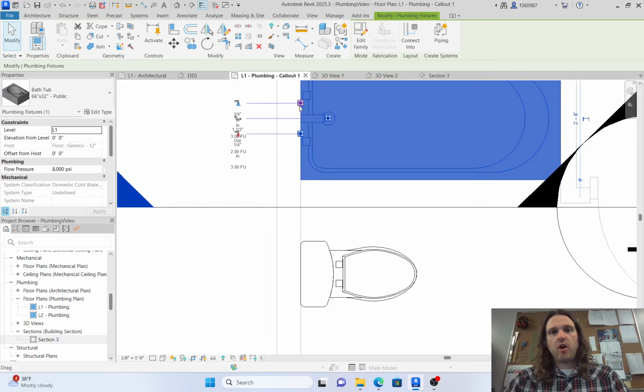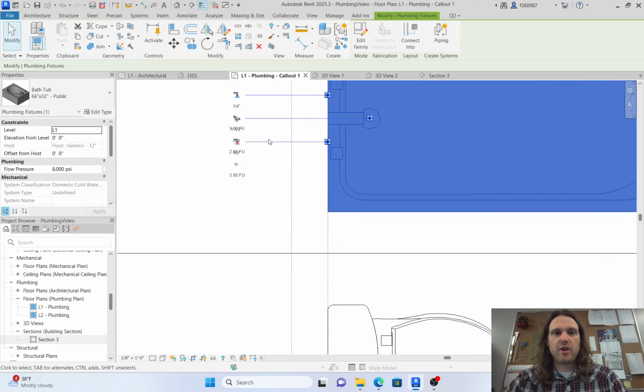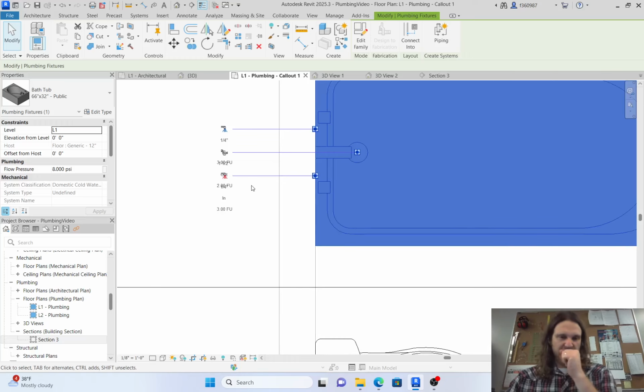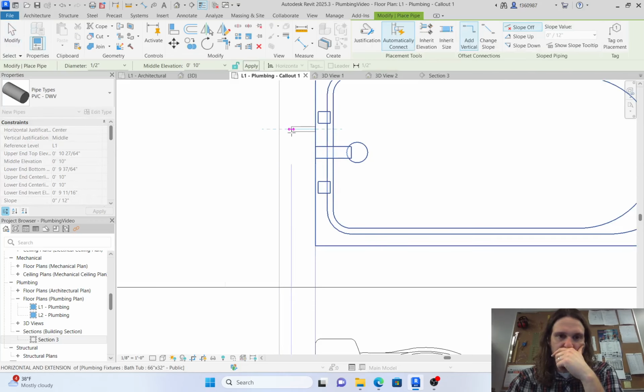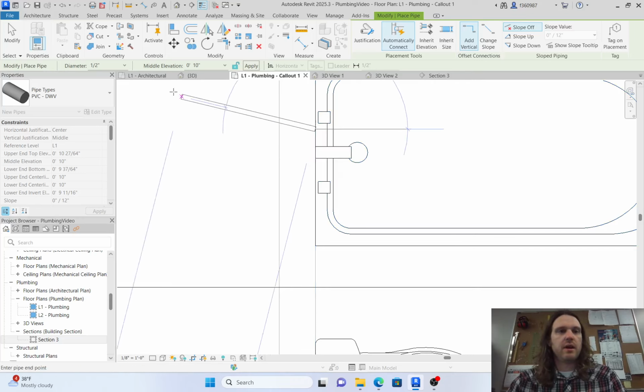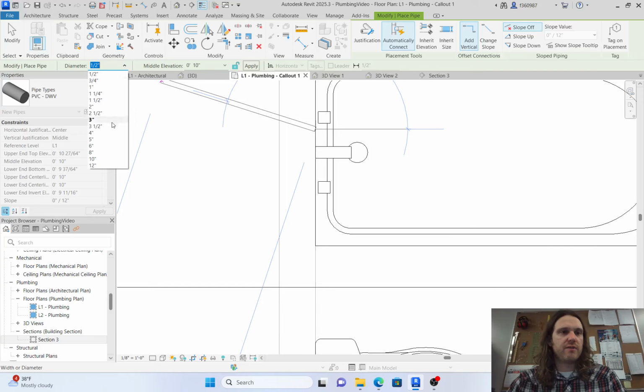Some of those are a hot water source or a cold water source that you can mount in the wall if your fixture, for example, doesn't have one of these add-ons. I don't know what this is called. I'll send you it. So we can click here. We'll do cold water first. So I'm going to click this little spout. If you're doing cold water pipes, what is the size? It says it's 1/2 inch. That's fine. A lot of this stuff, this cold water is 3/4 inch.